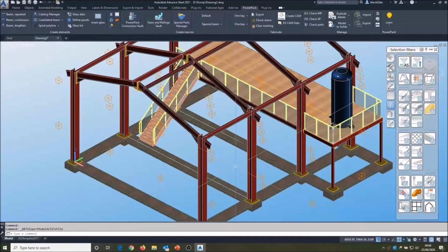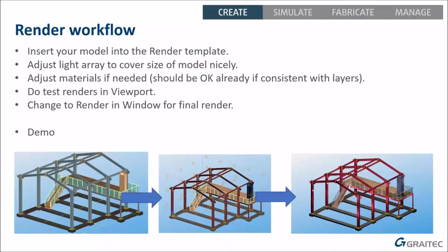And that will create you a new DWG, not this one, it doesn't change this file, but creates a new DWG that's just 3D solids with all the other properties that you've got. So we'll need those 3D solids on the next bit. So that's the AutoCAD rendering workflow. And you've got a better quality image, much like the right-hand side there. But I said there are other versions you could do that go higher quality or do different quality results.